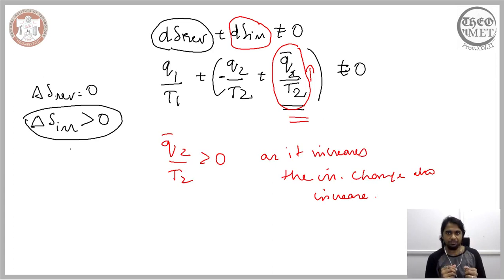We began with a simplistic example and we wanted to introduce some amount of irreversibility to it. We introduced this irreversibility by considering the change brought about by the heat that is lost, because we are fixing the heat that is being fed in. The degree of irreversibility depends on how much we are able to reduce the change brought about by the heat that is lost, and how much we are able to reduce this term depends on how much we are able to increase this term here. And this term here is what we refer to as the entropy change during the irreversible process.